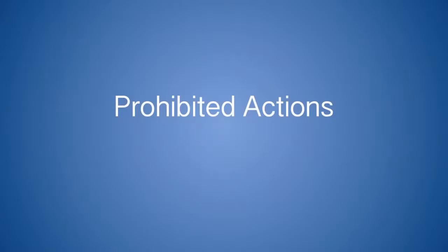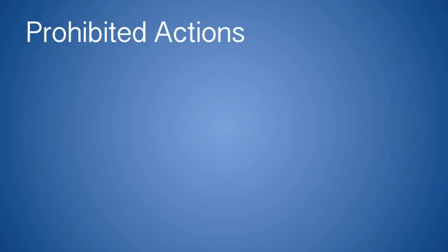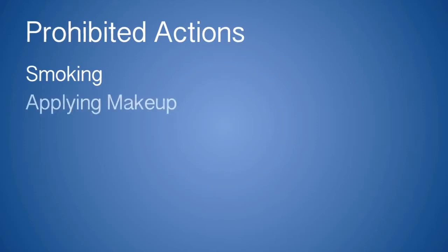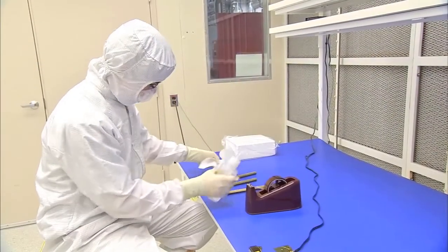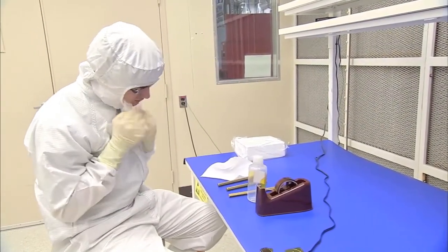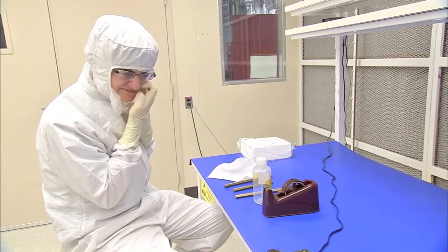Prohibited actions. While in the cleanroom, a number of behaviors are prohibited, as they introduce unnecessary contamination. Smoking is absolutely prohibited in the cleanrooms, as it introduces a vast number of unnecessary particles into a cleanroom. Applying makeup in the cleanroom is also prohibited, as makeup is a huge source of contamination. Touching one's face with gloved hands introduces skin and oil to gloves, which then gets transferred to hardware and other